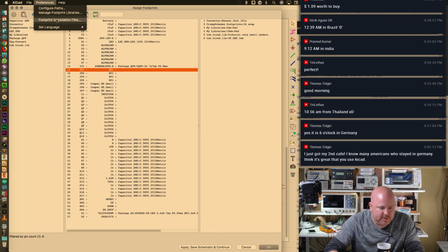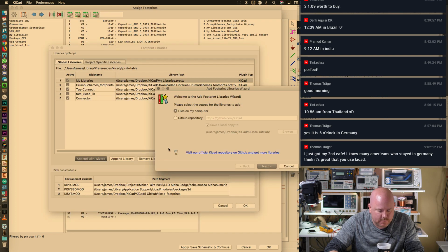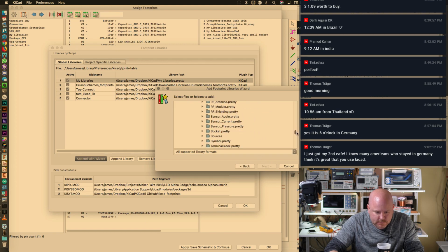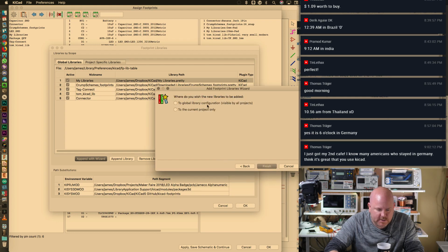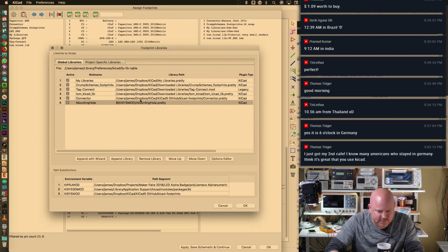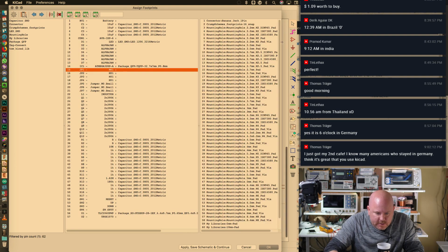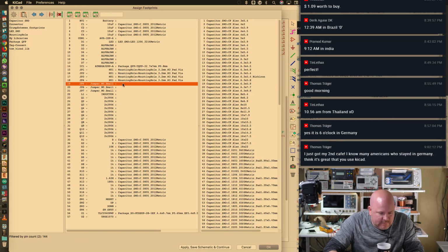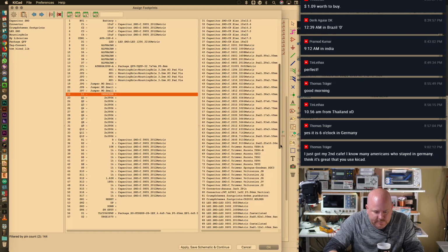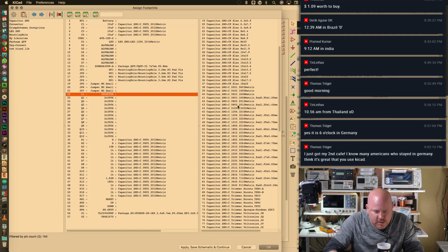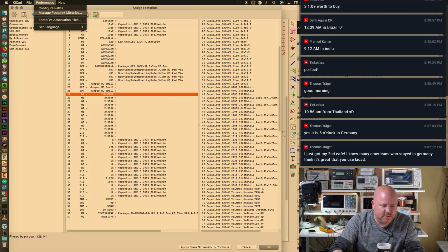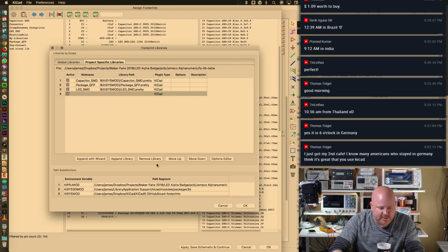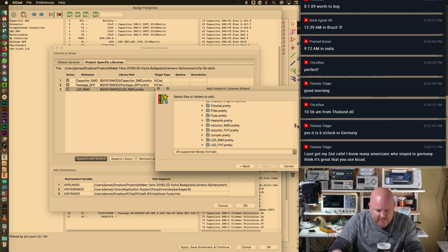M1, M0, so these are going to be mounting holes. I think I came up with one, and I'm going to start adding these to the global library because I use them, so why not? Okay, mounting hole, I need a 3mm, 3.2mm M3 pad via. Okay. Jumper, come back to that. Inductor, that can be a 12. Oh, actually, my inductor is a funny size. I've got to go look at that. Let's see if we have the inductor library.